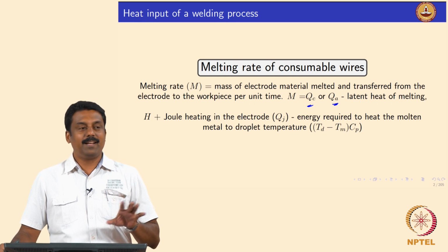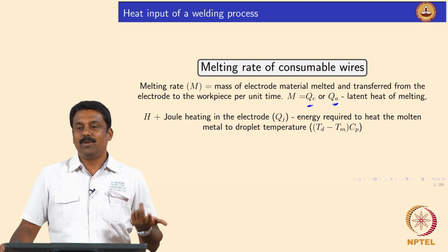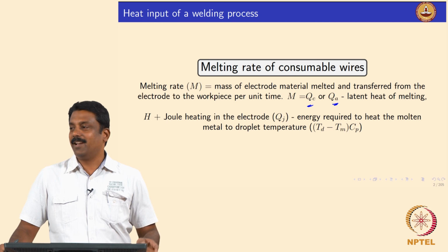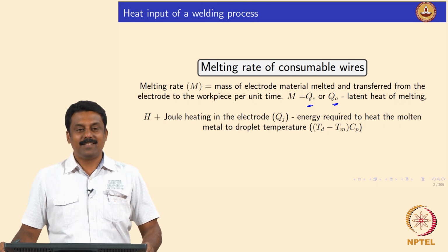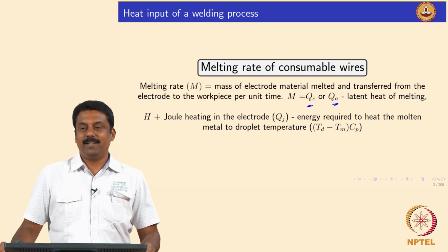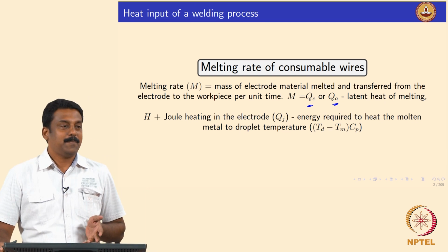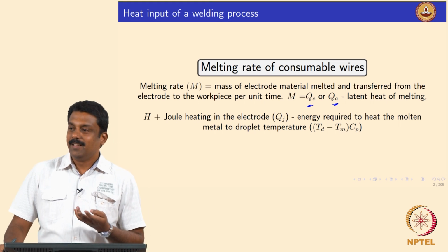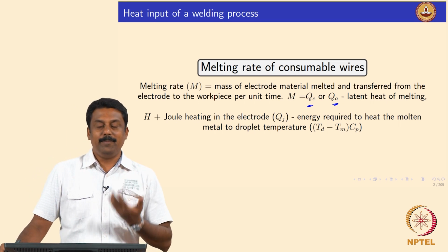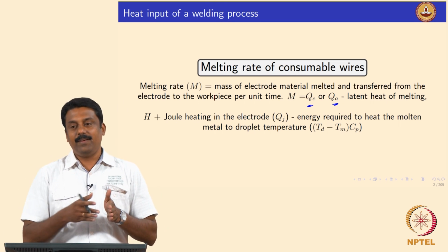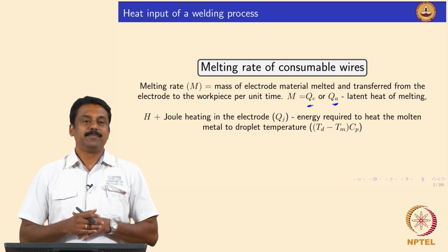It is not a thumb rule or a rule of mixture where you just weld with argon with a straight polarity and start depositing, because you are changing the physics entirely. So, it is extremely important to understand what these polarities mean and how they can interfere at varying levels.